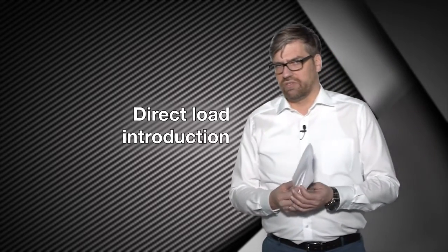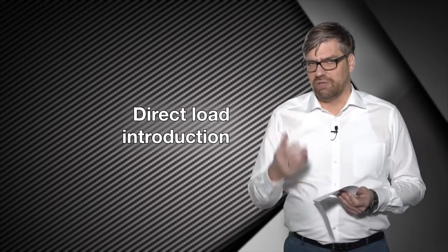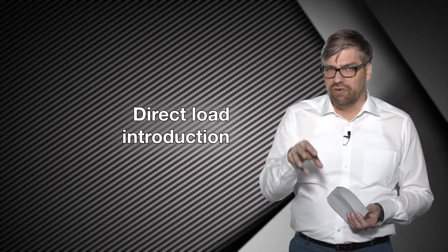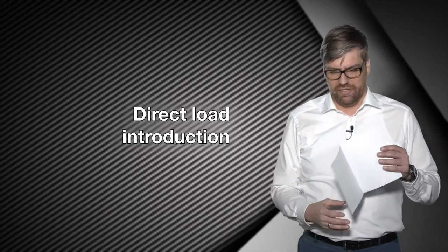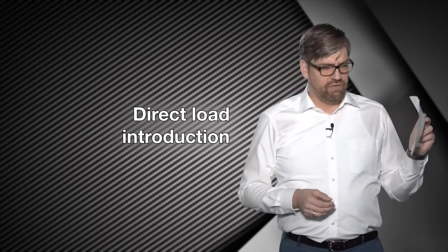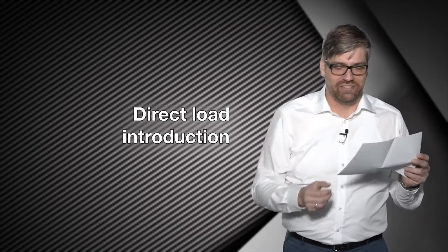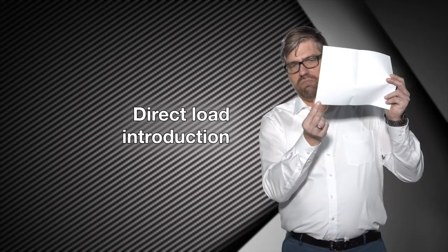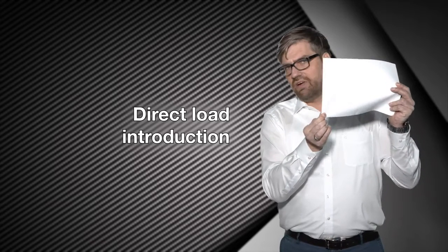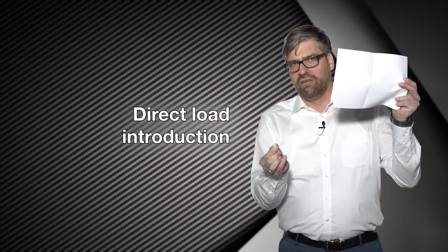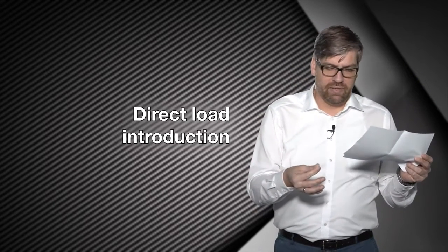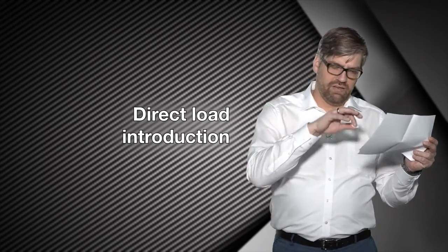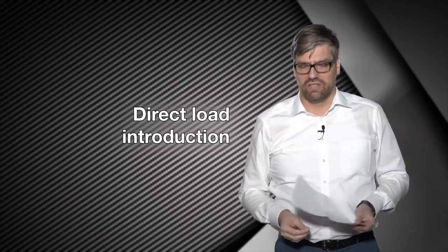And when you introduce loads in lightweight structures, that means optimized structures, you have to take a special focus on the load introduction points, because these points are always very critical. You have very thin structures, for example, again, the sheet of paper, a very thin structure, and the point where you apply your load always undergoes very large deformations and therefore fails at a very early level of loading, and therefore you have to take a special focus during design on these load introduction points.